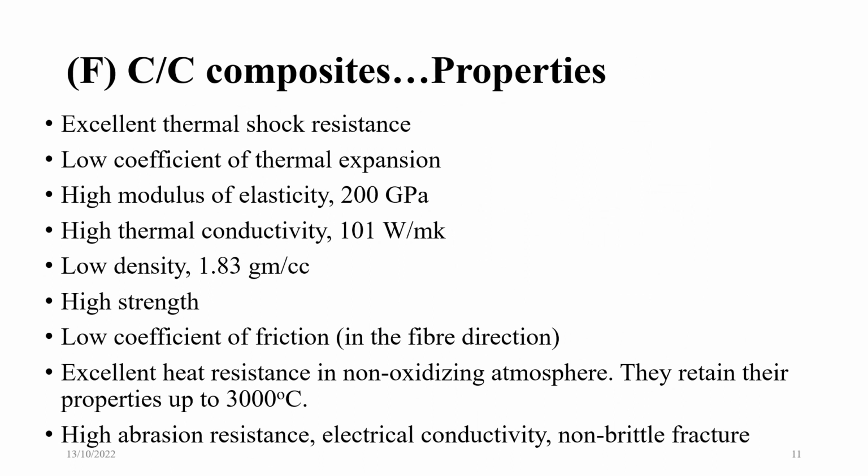Now coming to the properties, excellent thermal shock resistance, low coefficient of thermal expansion. We require definitely this for space applications. High modulus of elasticity, high thermal conductivity, low density, high strength, low coefficient of friction, excellent heat resistance in non-oxidizing atmosphere, high abrasion resistance, electrical conductivity and non-brittle fracture.